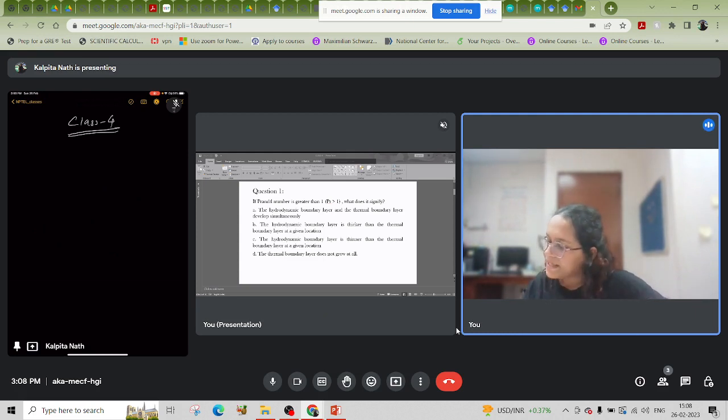Prandtl number is the viscous diffusion rate upon the thermal diffusion rate. It is also denoted as momentum diffusivity upon thermal diffusivity. So what does momentum diffusivity signify? Momentum diffusivity tells us about the material's resistance to shear flows, that is, different layers of fluid flow with different velocities, for example, due to the speed of the adjacent walls.